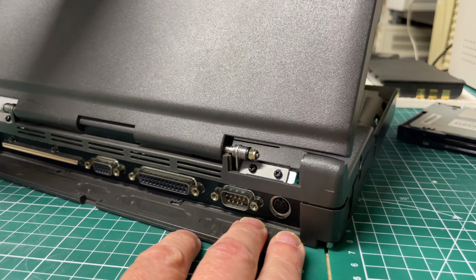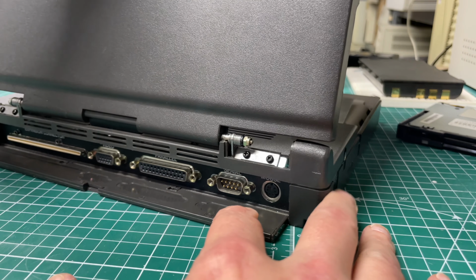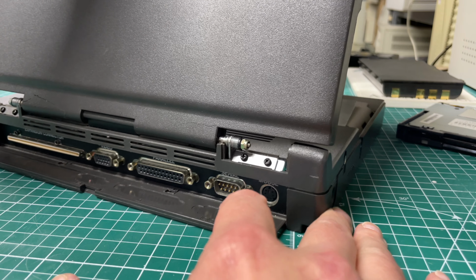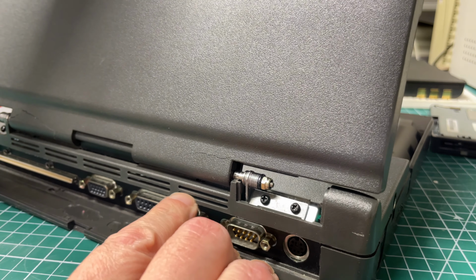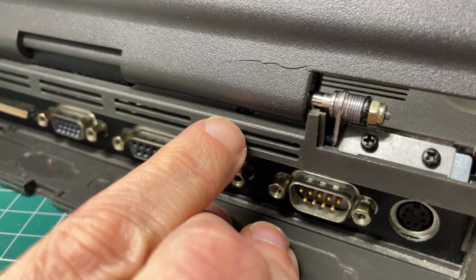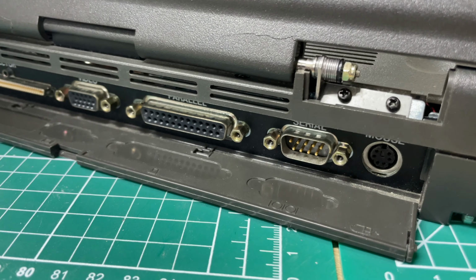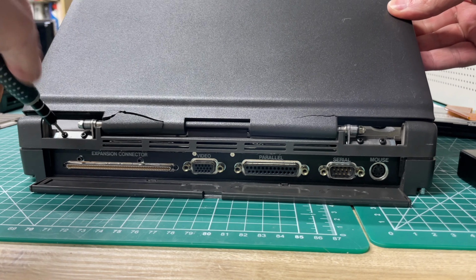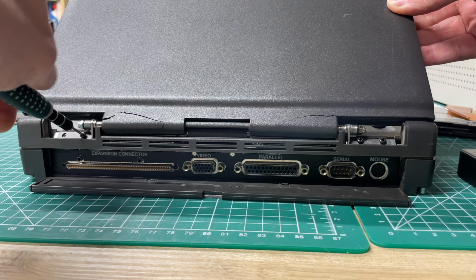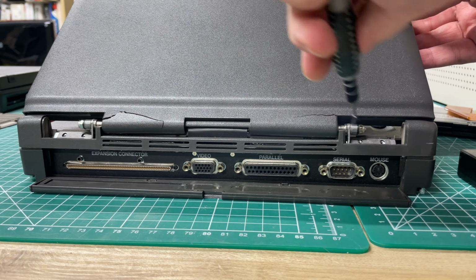And then there's always this one screw that you cannot find, because I was unable to remove that top cover for some reason, although I didn't find any visible screws. But when you look closely in between the LCD panel and the bottom of the computer, there's this one screw which is trying to hide. So in order to get to that one, we need to remove the 4 screws that we found earlier.